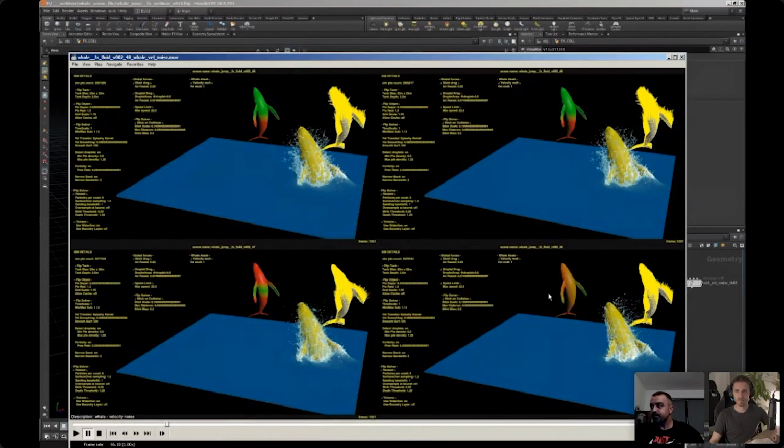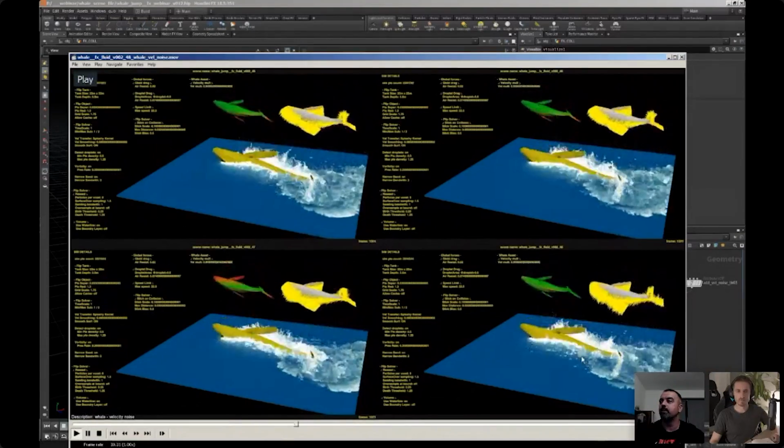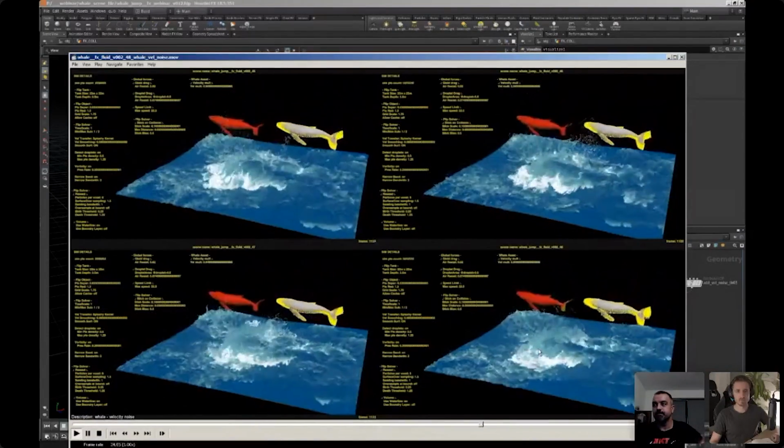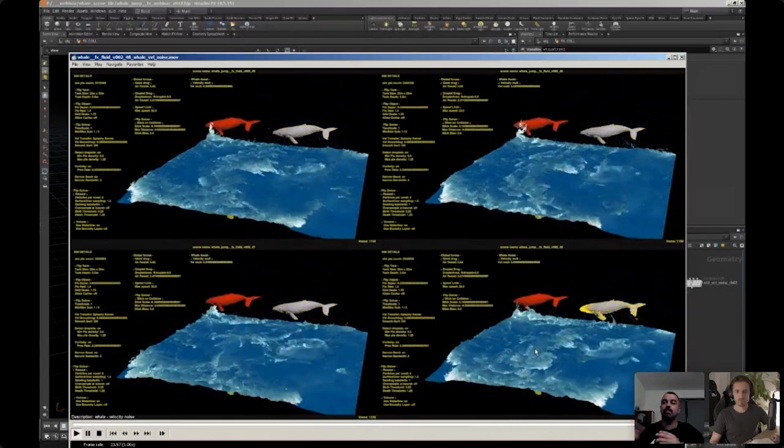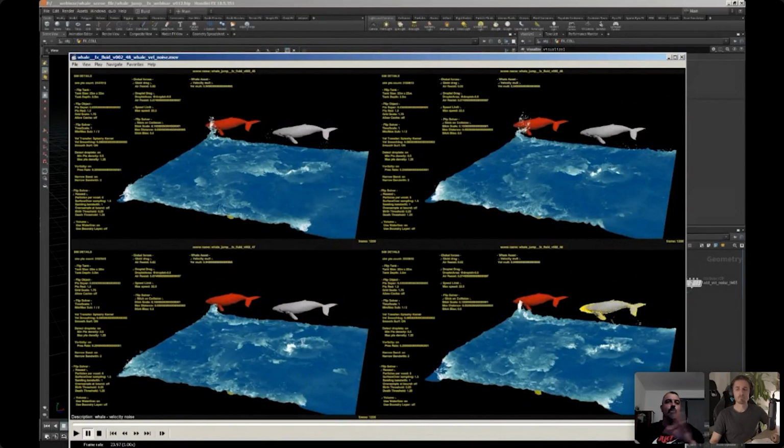With these simple tricks, you can see here, I used it, for example, where is the green? In my case, I have the noise. Where is the red? It's no noise. In this case it was only on the water surface, here it was all above the surface, and here it was in the middle section. But all these can immediately break your splash, and you're just adding control without changing any FLIP settings. It's all happening on geometry.